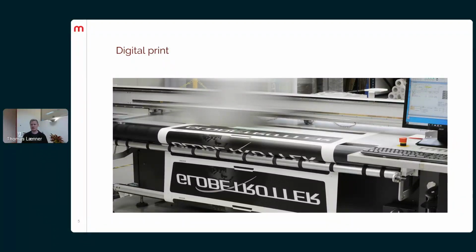This is also the printing technology we use for rapid prototyping and low quantity parts with many colors, for example. However, there are also some limitations with digital print. It's not as durable as screen printing inks. And as the digital ink is still a combination of small dots, it's not as lightproof compared to a solid screen printing ink.